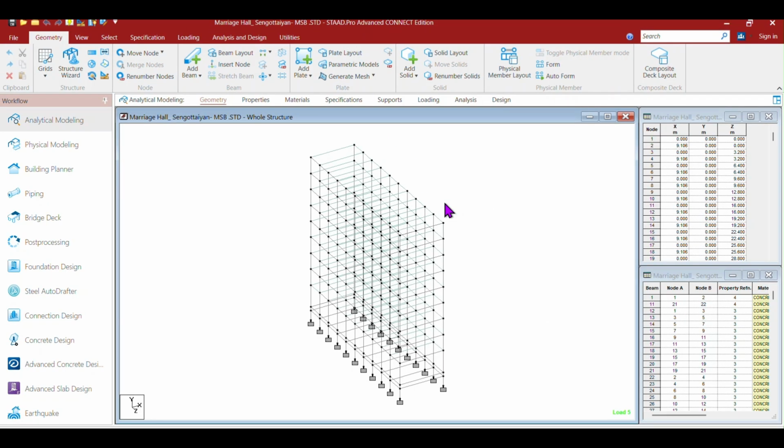Now we are going to see how to use the tool translate and repeat, or otherwise how to make a number of more floors, or copying and pasting the related subject. Now this is the sketch we have already created. There are floors of 1, 2, 3, 4, 5, 6, 7, 8, 9 floors we have modeled. But as per our requirement, this is about to be 12 floors. So 9 plus 10th, 11th, 12th. So 3 floors we are required to create more.